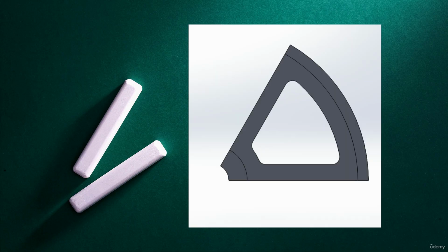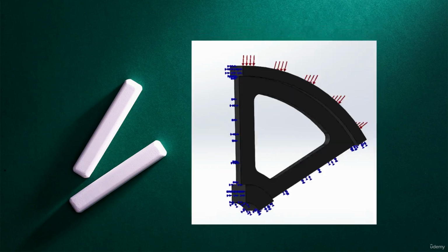The angle of the wedge is arbitrary, but using a small angle may result in a bad element shape, especially when there is no hole at the center of the model. The symmetrical restraints are applied to the cut sides of the wedge, to the faces of the symmetry. So for solid models, they guarantee that every face that is coincident with a plane of symmetry is prevented from moving in its normal direction.